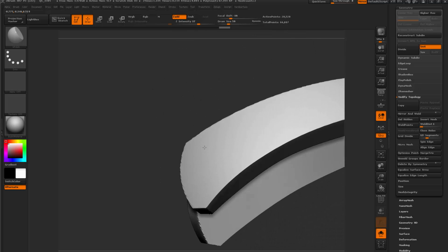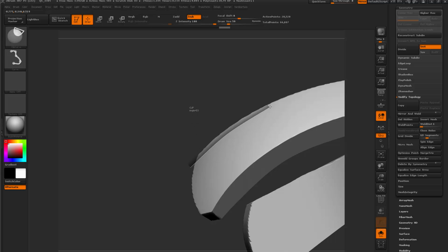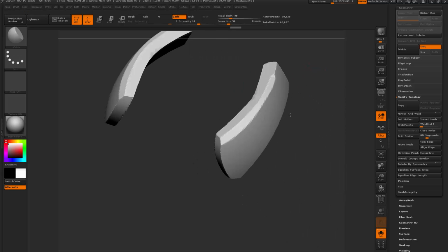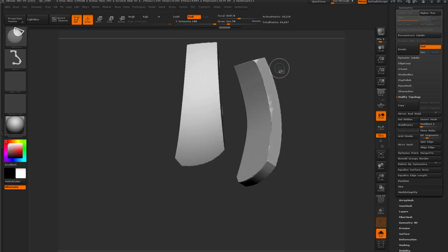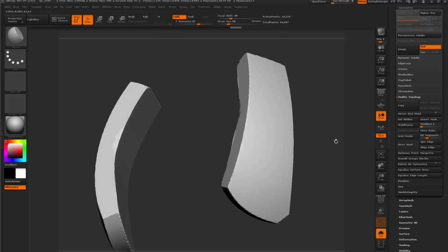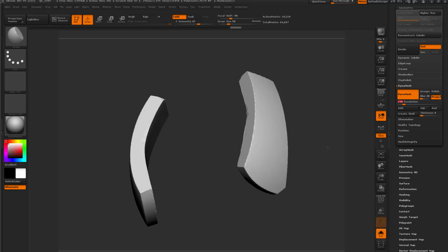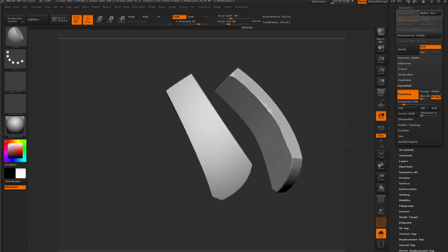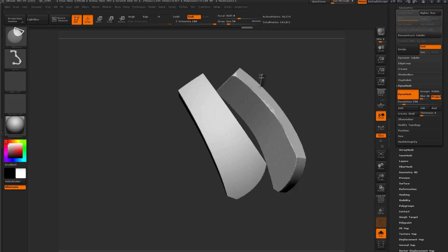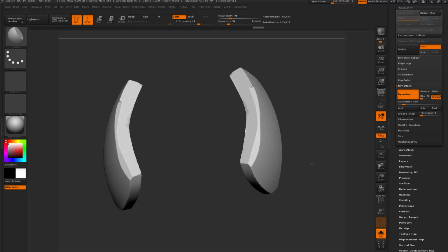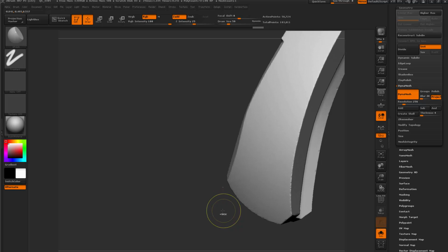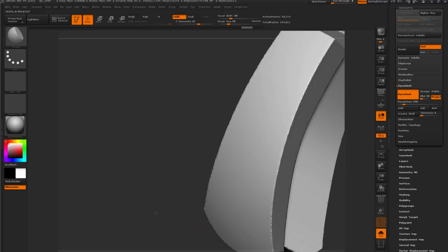Let's say I want to bevel it then. To bevel the edge, I can use Clip Curve to clip the edge. I don't want to bevel it all the way through. I want to have that little cut there. So that's what I'm doing here. Now, if you want to have cleaner results, you want to have higher resolution on the DynaMesh. So let me just double my value there and then DynaMesh it again. And hopefully this time I will have better results. Okay, sure, that's not cutting into the area I want it to be.